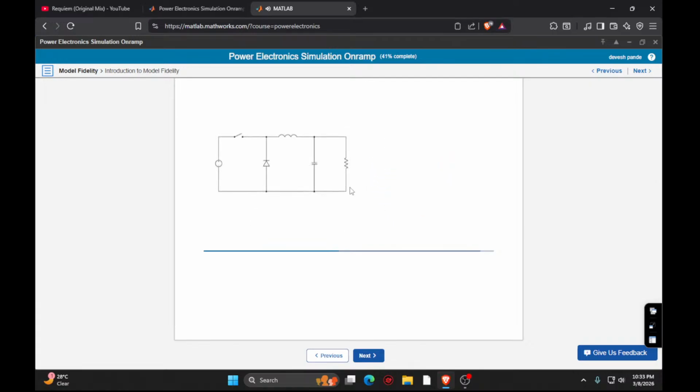When modeling power electronic circuits, it's particularly important to choose the appropriate model fidelity for the purpose of your simulation. In particular, because of the high-frequency switching that defines power electronics, the device outputs exhibit both a slow overall response and a much faster oscillatory behavior. This is known as a stiff system and can be difficult for numerical tools to solve. Therefore, it's common to choose lower fidelity models when applicable to improve simulation performance.